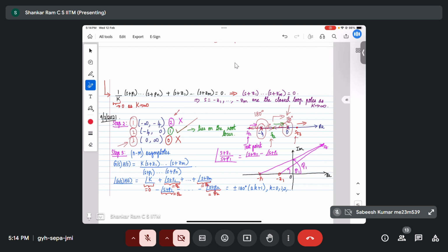So now by the same logic, if we count the total number of open loop poles and open loop zeros on the real axis to the right, how many do we have? 0, right? And we take it as an even number for this particular discussion. Or, in the context of this discussion, we take it to be not odd. Okay. So consequently, what will happen?